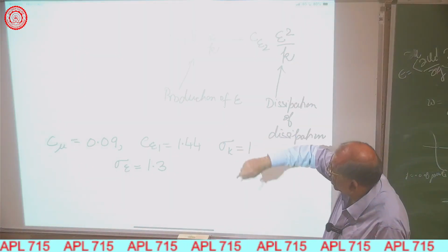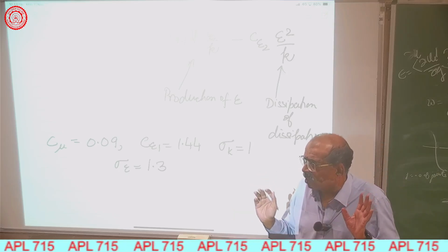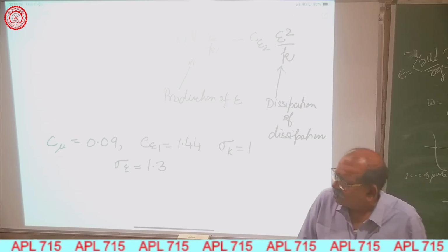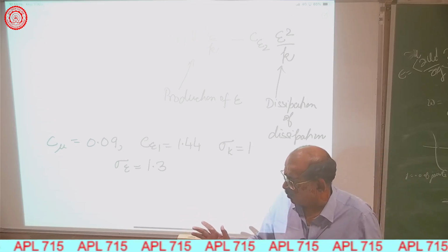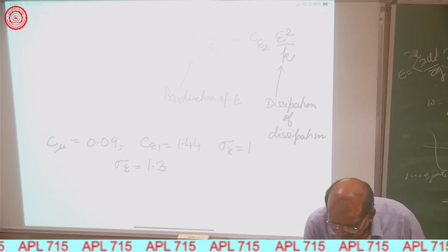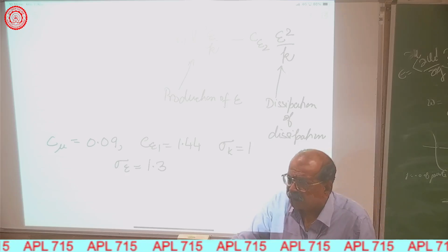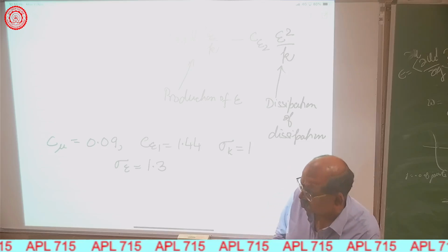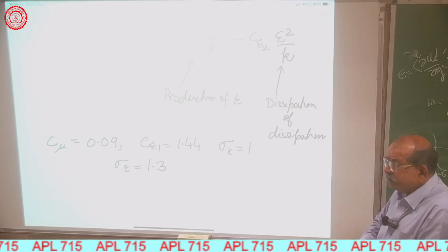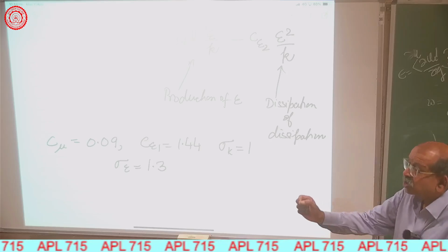But before that, now suppose with given this K epsilon model, you come across a situation where you have no idea about the flow. Let's say you have to model flow in a box where there are many chips mounted. It's a complex geometry and you want to model this flow. Now you don't have any mixing length for this, because should you take the mixing length from the base or the distance from the chip?